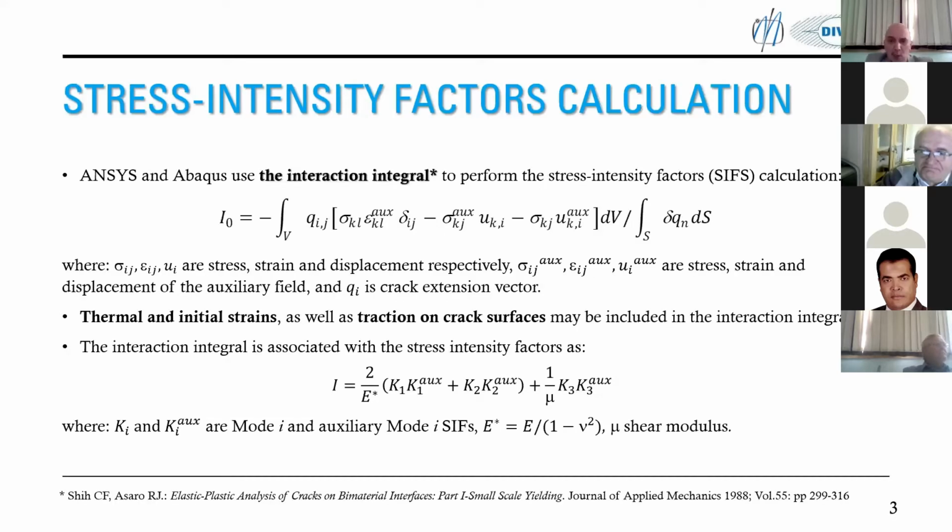Okay, this is just a short reminder about how stress intensity factors are calculated within finite element software. So basically, we use interaction integrals in some form. You can see one form of that integral here on the screen. And then using the values of this interaction integral, we can estimate stress intensity factors using a formula which you can see at the bottom of the screen.